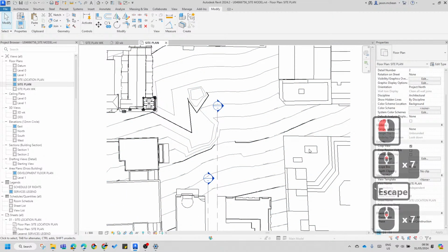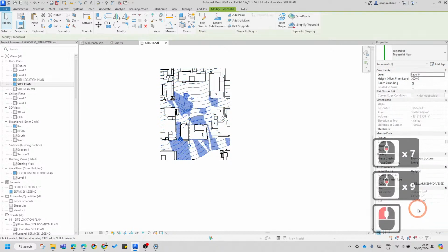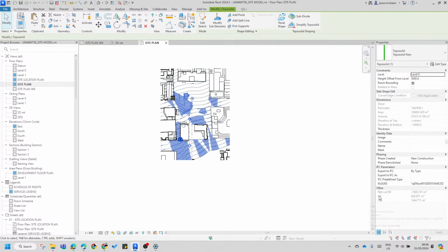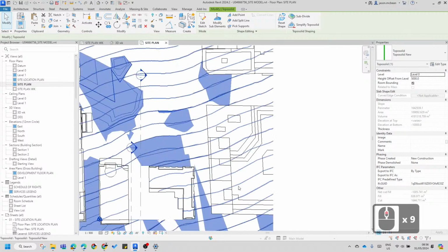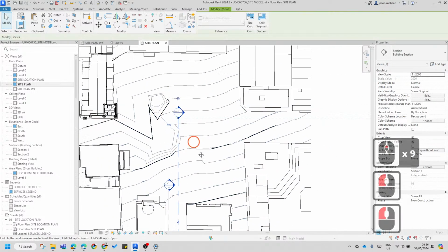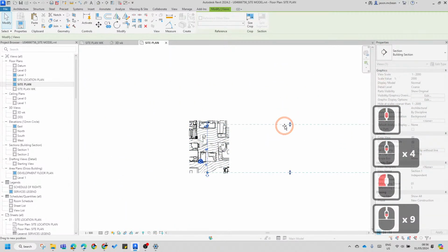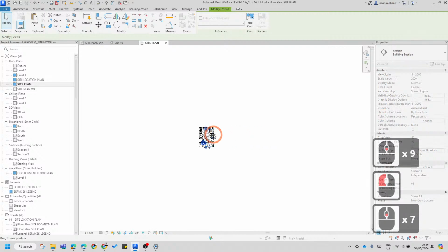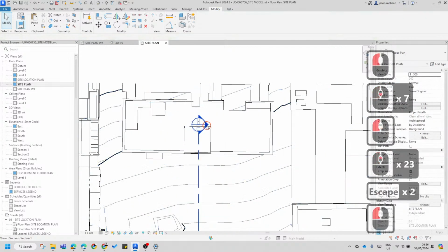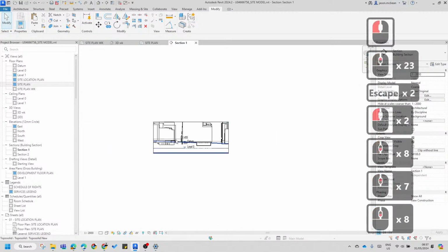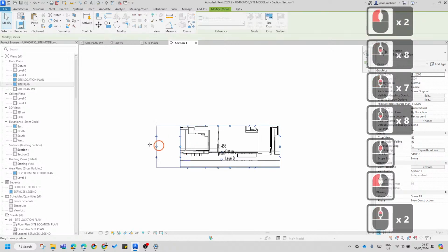And guess what happens with your cut and fill? So when I select these sites, see this? Yes. Fill. We've cut 16 cubes. Yeah. And we've only filled. Yeah. You can start also balancing that. So that's very neat. Okay, so we can start playing with that dynamic. Now, what you do is you use these sections. So you're going to start using these to start exploring your site.